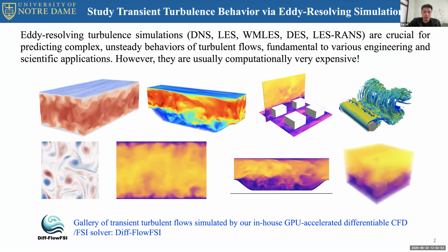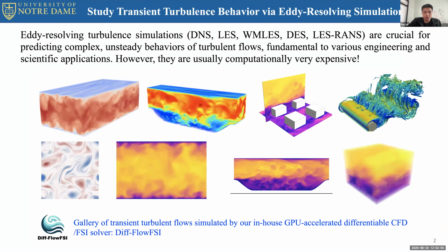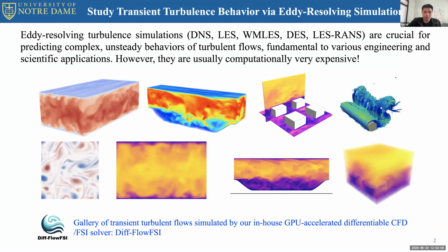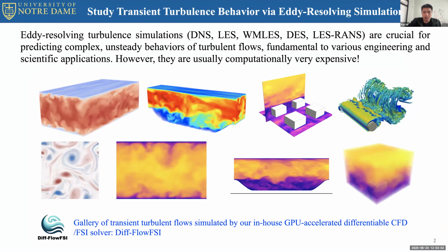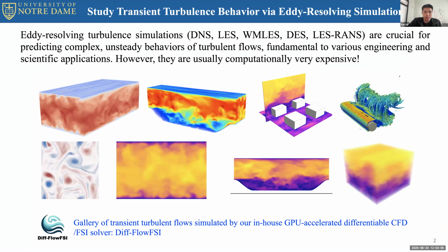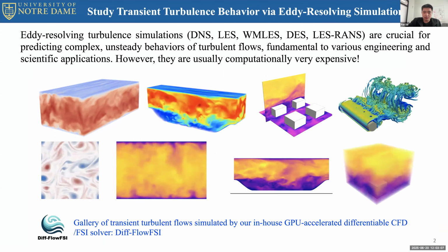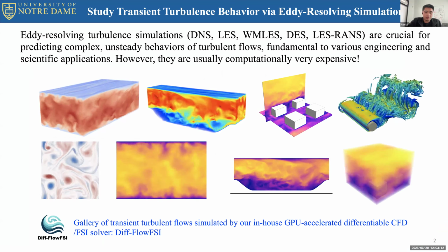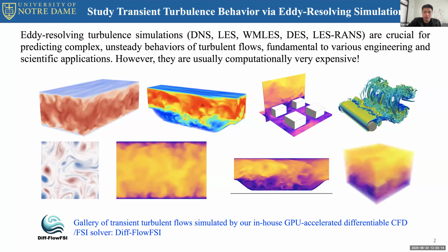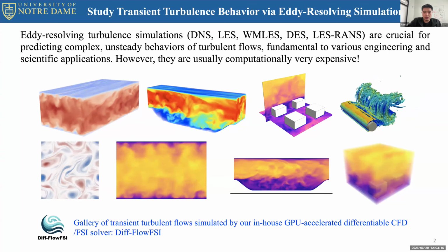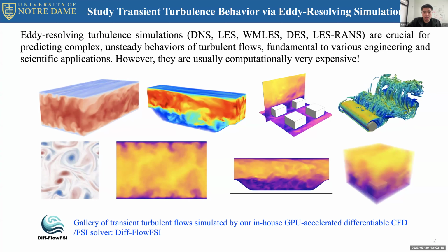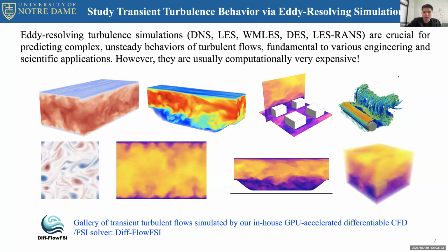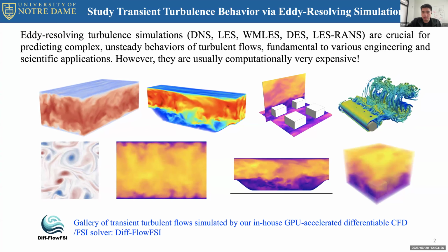To give a little bit of background, in fluid mechanics, eddy-resolving turbulence simulations, such as direct numerical simulations and LES, are very important to predict complex unsteady behaviors of turbulent flow. This is fundamental to various engineering and scientific applications. However, traditionally, those solvers are very time-consuming to compute, majorly because those simulations typically have very high spatial and temporal resolution.